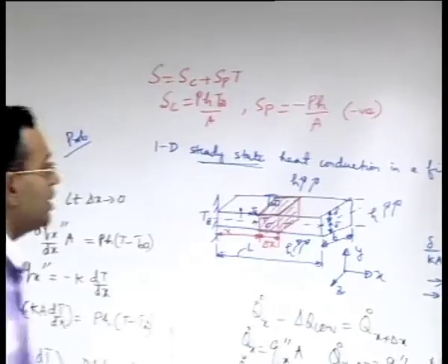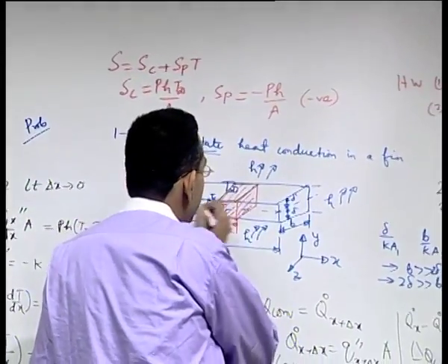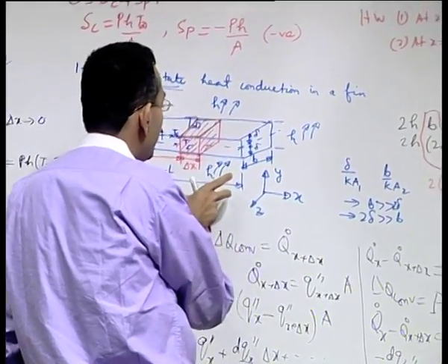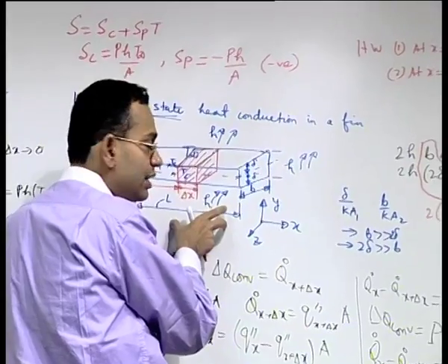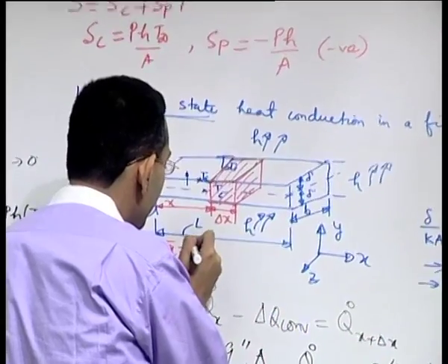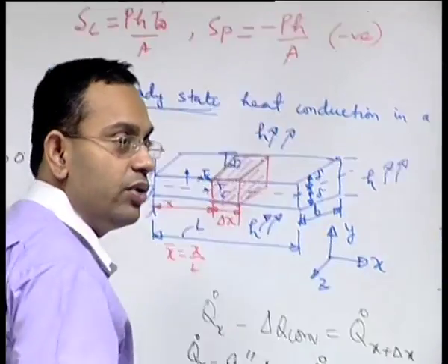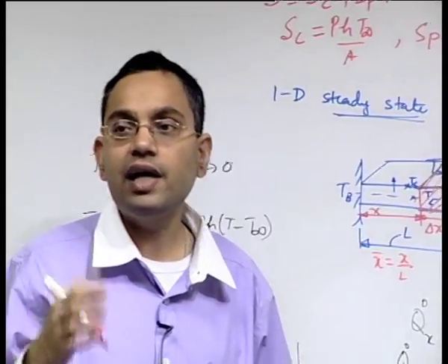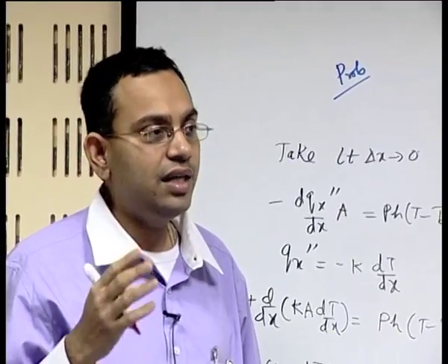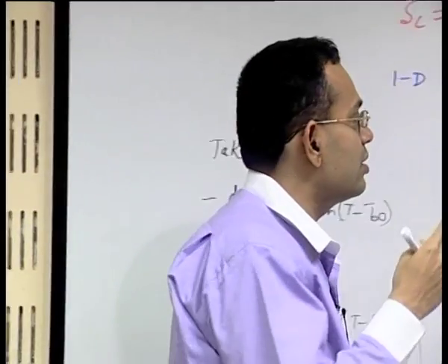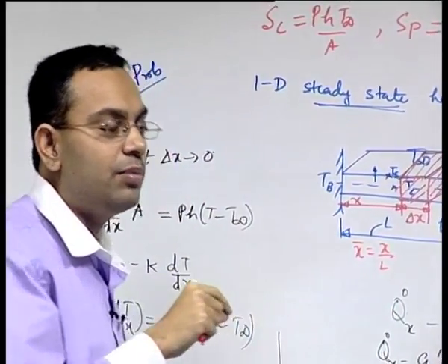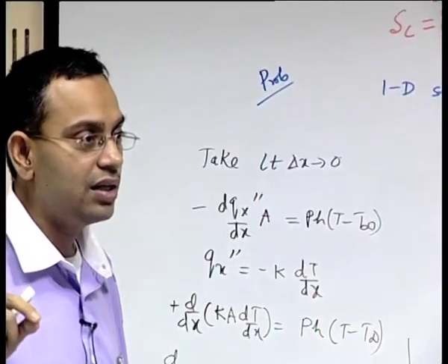So, that is the first thing. You can discretize it into a number of control volumes. Say you non-dimensionalize the entire equation, so that your non-dimensional x, which is x by L, will be between 0 to 1. You can divide it into say 5 control volumes and then you will get the requisite number of grid points. At each grid point you solve for the temperature by using the finite volume method.